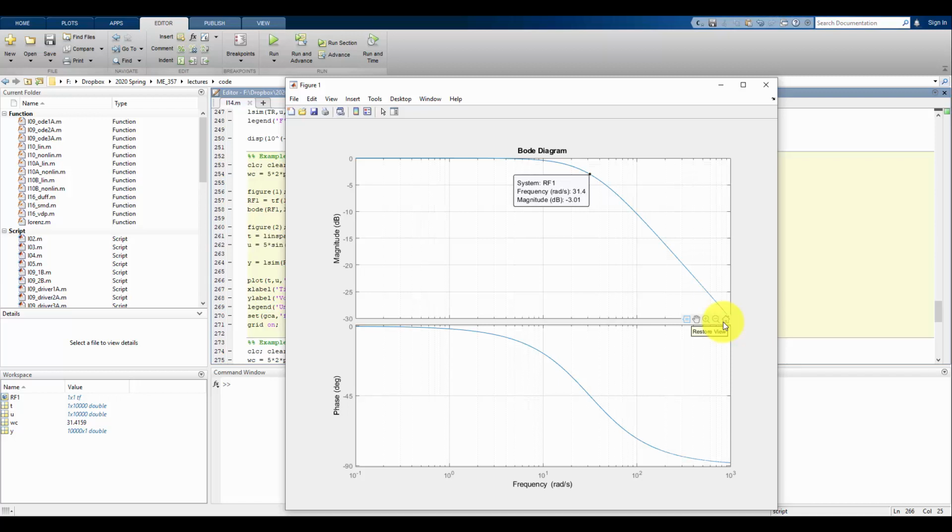This real first order filter, passive filter, doesn't do that. So notice that we have, again, this is where we see this roll-off concept, that the magnitude is going to start declining. It gets to -3 decibels at the cutoff frequency, and then it continues to decline. So any frequencies we would have in this mid-range here are going to be a little bit attenuated, but not too much. And that's going to keep getting more and more attenuated at those higher frequencies.